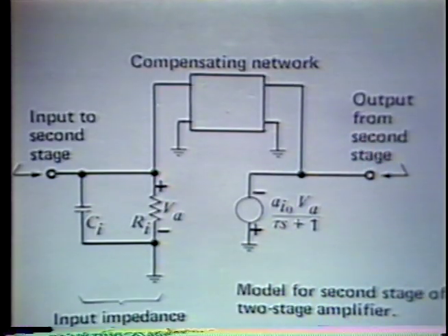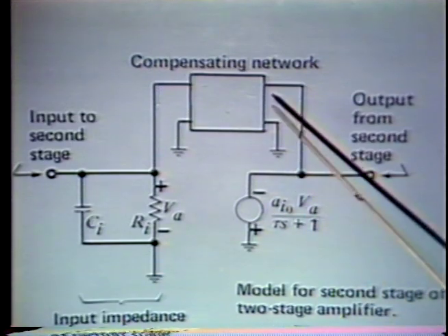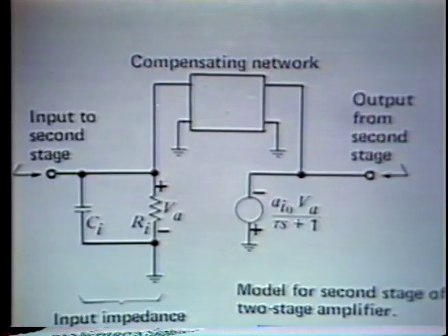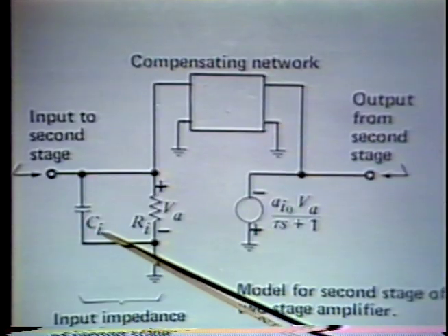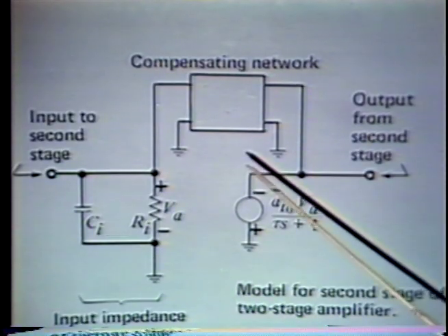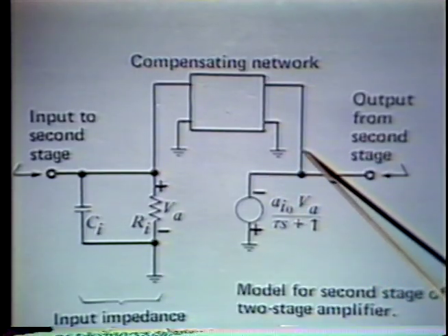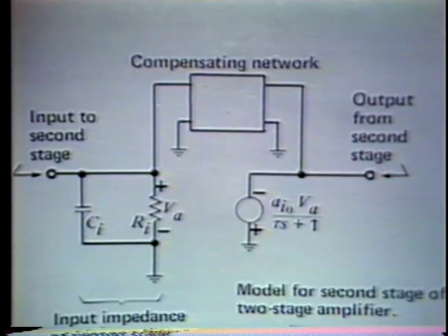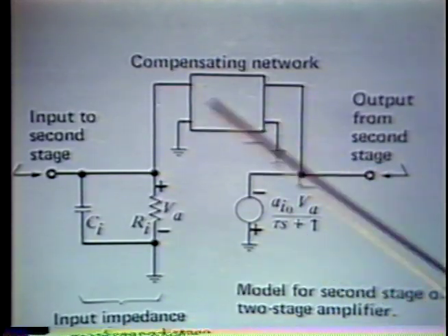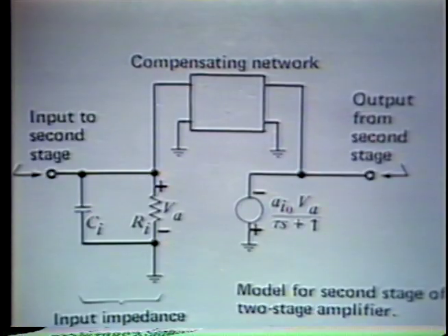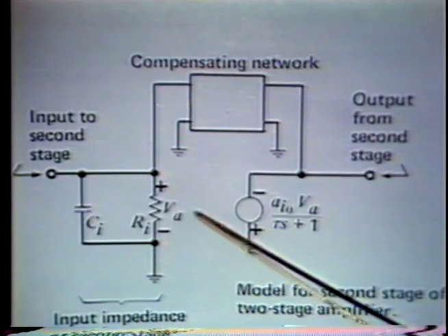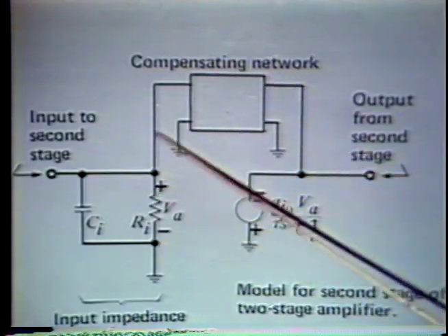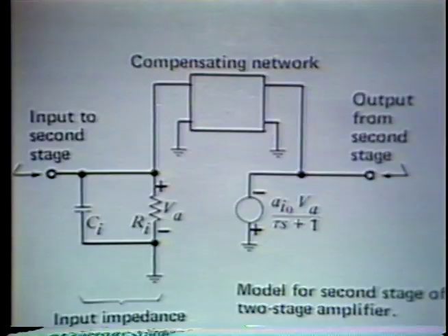We basically have a capacitive divider at high frequencies that involves the effective capacitance from this point to this point in the compensating network working with the input capacitance to the second stage. So we get simply some fraction of the voltage at the output of the second stage applied back to its input. That's fine. The minor loop is quite well behaved under those conditions because we have effectively a single pole roll-off, this pole, in the vicinity of the minor loop crossover.